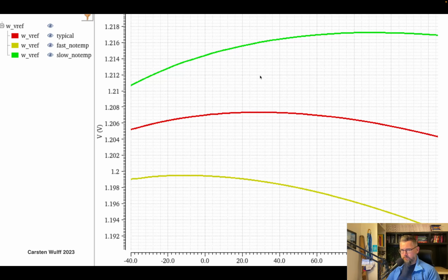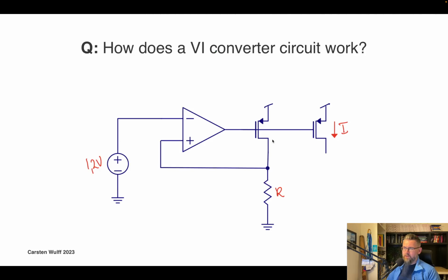And I can ask another question. Hopefully I remember in the lectures to ask you what you think, but I believe also the direction of the bipolar, or how you lay out your diode or bipolar device on the chip, will matter for this constantness over temperature.